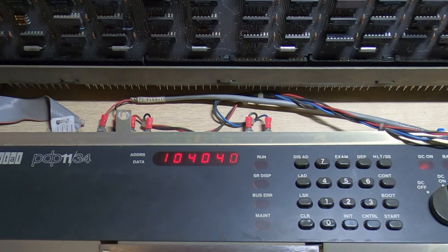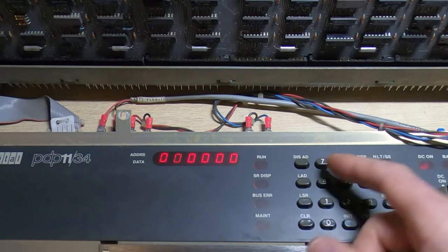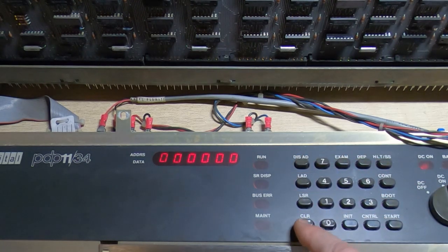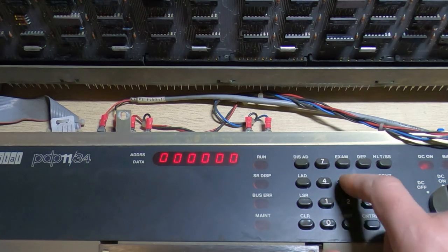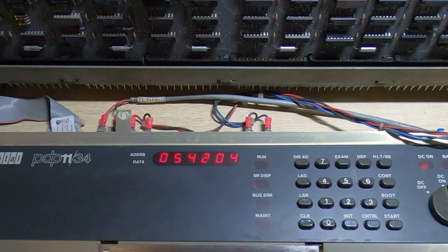One other thing we can do as part of this testing to try and pin down where the error might be coming from, it's obviously coming from the drive, but what's causing it? If we reset the drive, again I heard the stepper wind back to the home position. Okay, what we can do now is restart the same function, the write sector function, so we send a value of 5, examine the register, notice we've got a value of 2, that's the TR bit set.